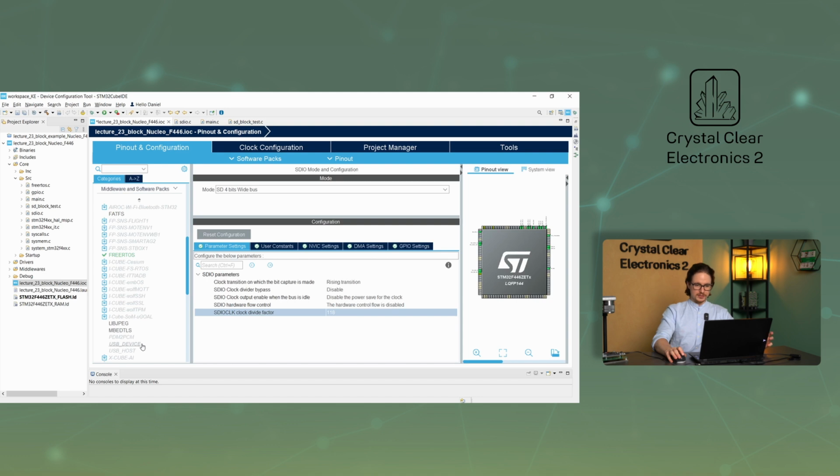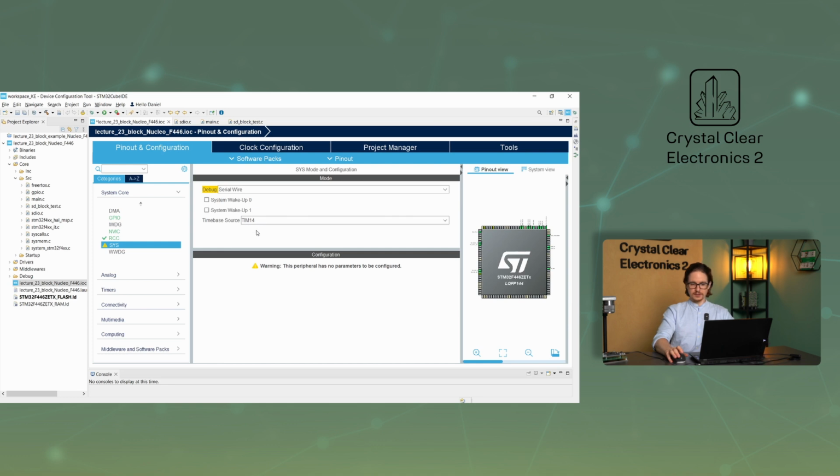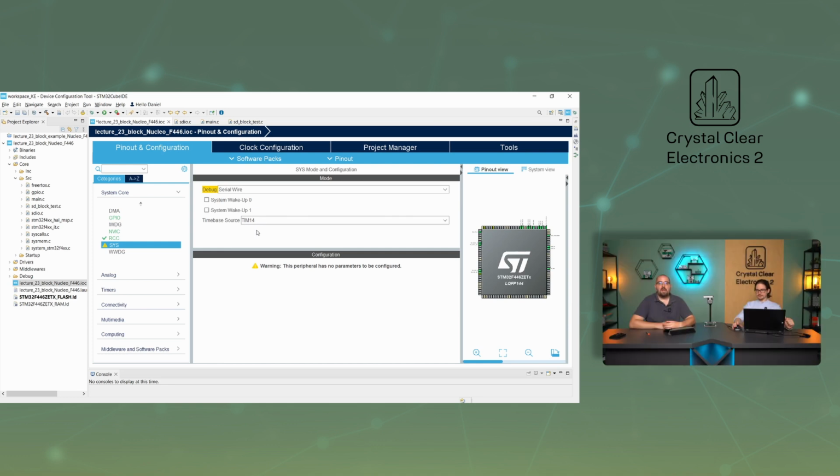For the rest of the curriculum, the use of FreeRTOS will be essential. So just to get used to it, we will be using it now. In the attached project, TIM14 is used to generate the health timestamps. SysTick is used by FreeRTOS. We will then regenerate the project to be on the safe side.